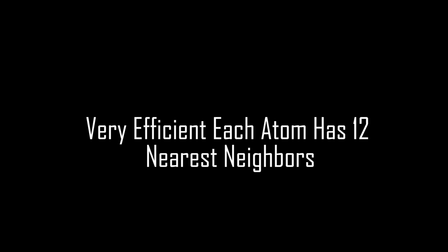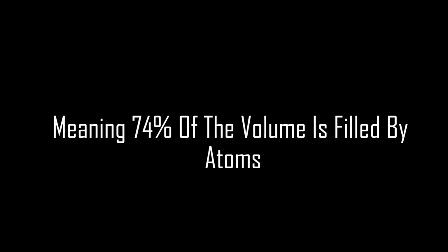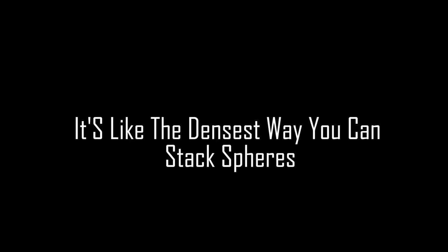And it's efficient packing. Very efficient. Each atom has 12 nearest neighbors. That's its coordination number. And the atomic packing factor, or APF, is 0.74, meaning 74% of the volume is filled by atoms. It's like the densest way you can stack spheres.